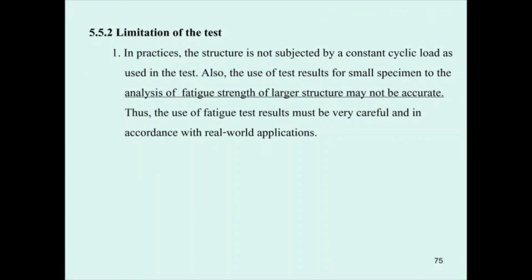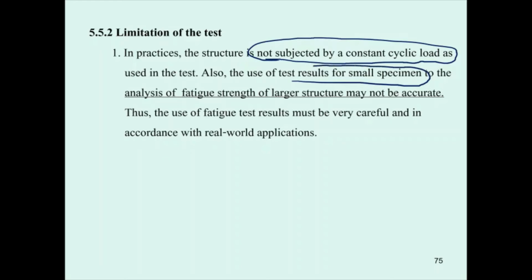Okay, the limitation of the test. In practice, the structure is not subjected to constant cyclic load as we use in the test. So when you use the testing result, you need to be very careful, especially for small specimens. That may be inaccurate.